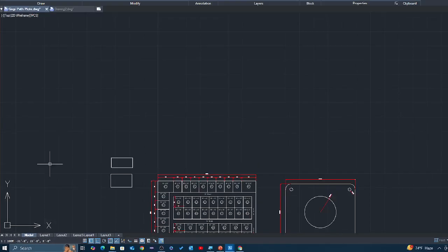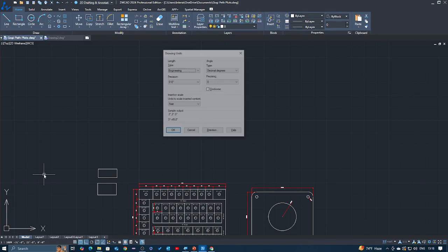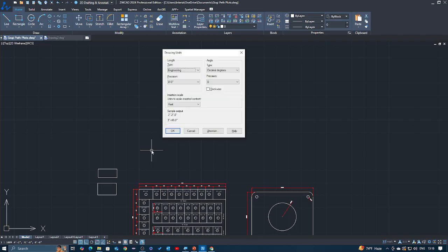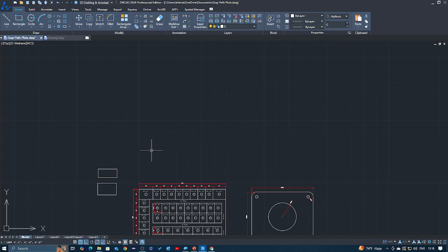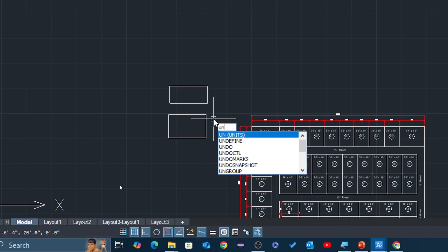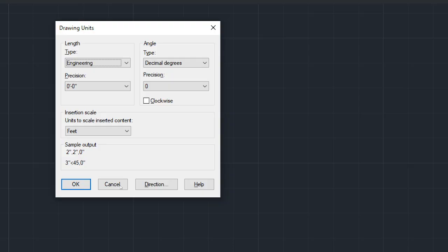If you type also, what is going to happen here? I will show you. You type it, you are never going to understand what is happening here. That is why you have to always activate dynamic input, then you type it. Now it is showing some suggestions on the screen, enter it, then that command will be executed properly.